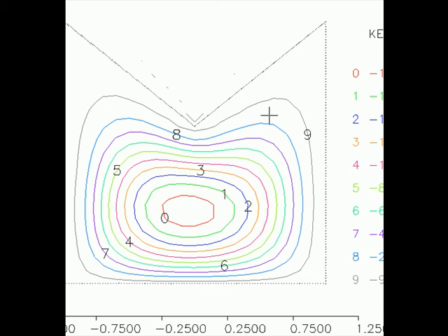That's phi sub x comma phi sub y, and the velocity field is phi y comma minus phi x, so the dot product of the gradient and the velocity field is 0, which means that the velocity field is perpendicular to the normal to the curve, i.e. it's parallel to the curve. So the constant stream function basically shows the streams of the velocity field.